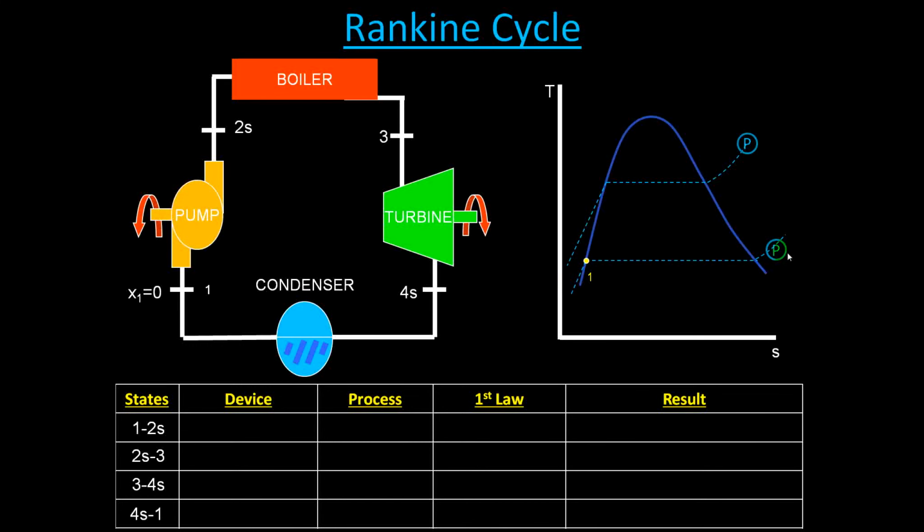So before we come into the pump, we'll be at a low pressure line. And so we'll go through a pump. The purpose of the pump is to do compression, to increase the pressure of our liquid. Because it's an isentropic pump, we can see here on the vapor dome that since this is temperature versus entropy, the entropy is constant. It goes straight up until it gets to the next pressure setting, which is the high pressure for the pump at state 2s.